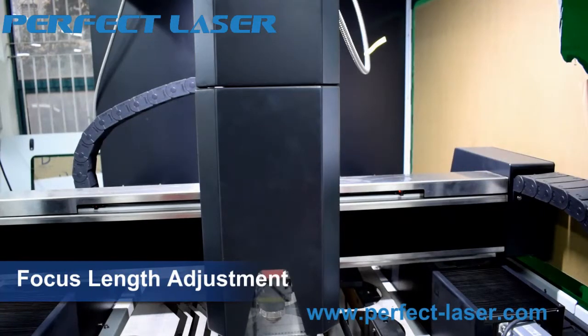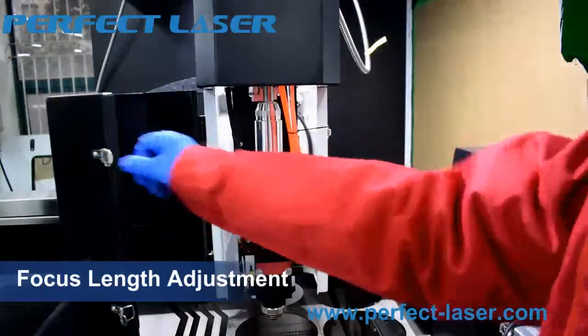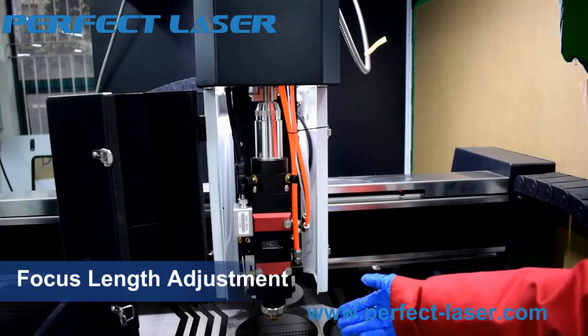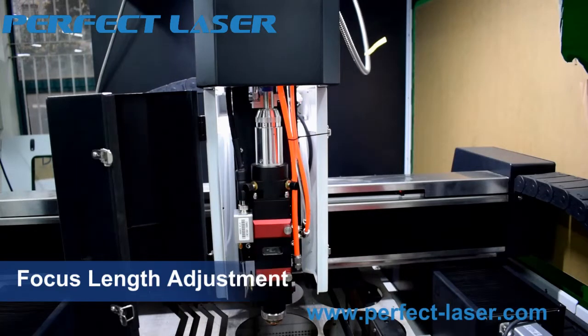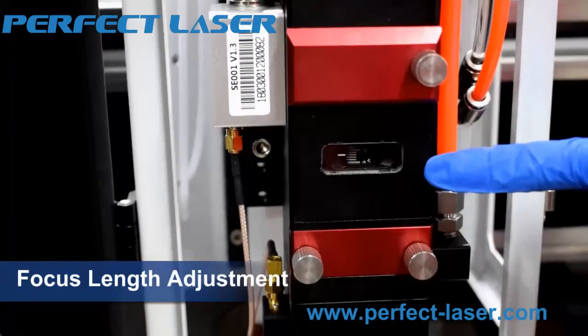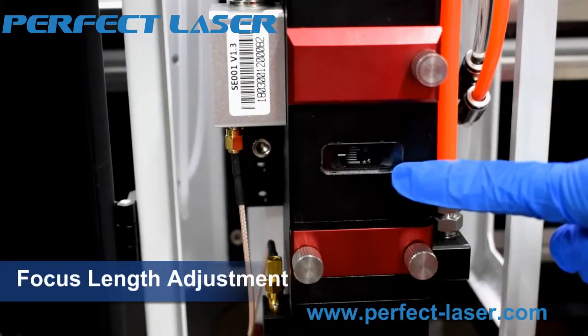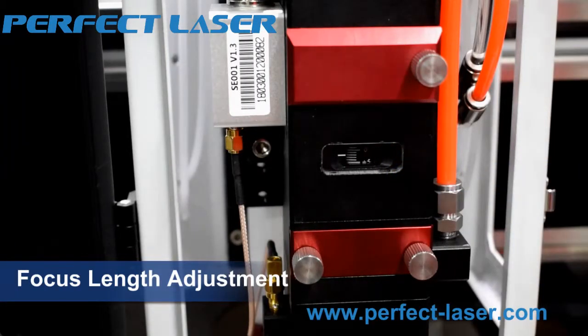Now I will teach you how to make the adjustment for the focus length. The focus length setting is in the laser cutting head. Firstly, let's open the cover. As you can see, this is our laser cutting head. And you can make the head go up and down. Firstly, you could raise the laser head. As you can see in this window, this is the scale, and before delivery, we make the adjustment for that.